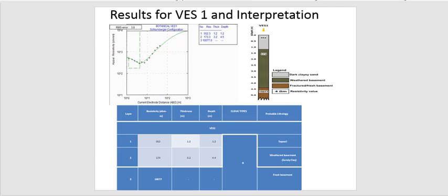It has a decisive effect on the stability of foundation and seepage. So coefficient of permeability is what we actually look for, and which helps us in our job. Coefficient of permeability is a measure of the ease with which water can flow through soil media. It is the average velocity of flow that will occur through a total cross-sectional area of soil under unit hydraulic gradient.